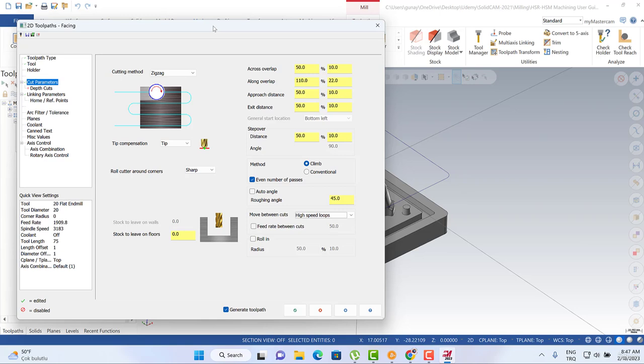If you use sharp corner toolpath geometry, it means that you're going to get an uncut process, okay? This is not simultaneous, okay? You need to stop and then you need to move, so that is not good.